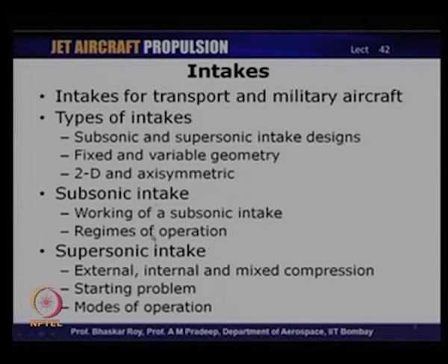We have seen the working of subsonic intake and operation of subsonic intake in different operating conditions like takeoff or cruise. In supersonic intakes, we had discussion on three different types of intakes: the external compression, the internal compression, and the mixed compression intake. We have discussed the starting problem associated with supersonic intakes, and also the modes of operation of supersonic intakes like subcritical, critical and supercritical modes.